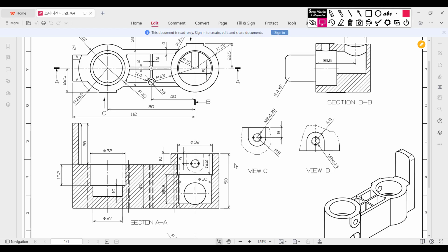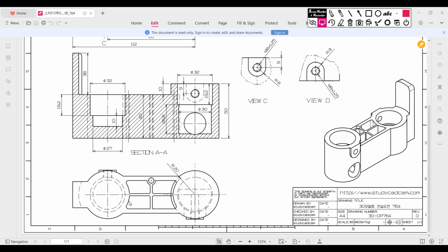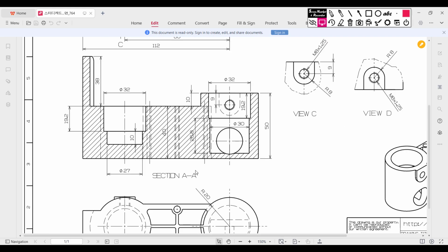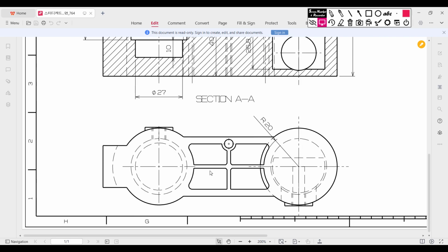Now let's go back to our sketch again, and this time in our sketch we can see that we have a circular portion here. For drawing this circular portion, if we look back a little, let me zoom in a little. Here we can see this circle's center line is along these two lines. So that means it is 4 unit distance from here, or we can draw a center line here, so it gets along the center point of the circle.